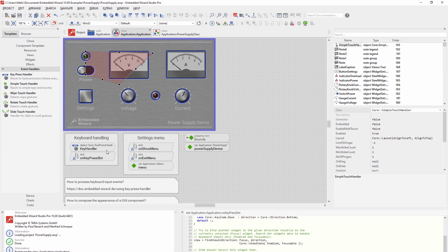views, for example. I have to be honest with you, this automatic and magnetic alignment is something which someone likes, and there are some out there who do not like that. If that is too annoying, then you can simply disable that. This can be done in a permanent way, so that means by disabling that here with the magnetic snap mode, by pressing that button here, or by pressing Ctrl G on your keyboard. And as you see, this has now been permanently disabled.